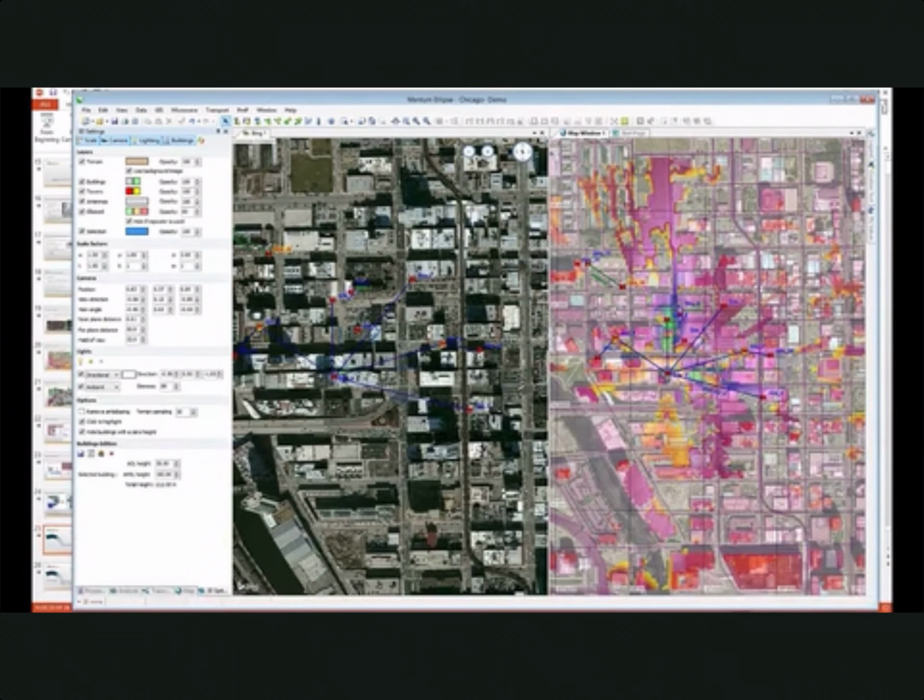Okay, for penetration, you use... Now I don't have any example here, but if you have a single knife edge or a small building or a tree or something, then it's just to do like you normally do. You select the knife edge method and calculate the loss.